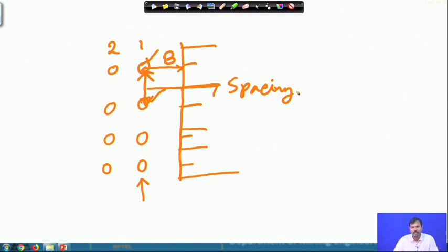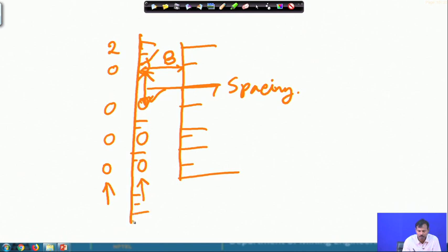Similarly, if you look at the second row of holes, the first row of holes should be blasted ahead of the second row, and so after blasting the first row using a delay detonator, you will find your free face will be shifted to this position, and thus the burden for the second row of holes will be this one.